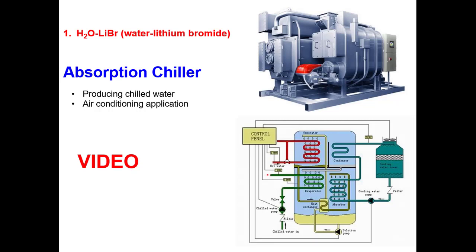can take the heat of that chilled water, I mean the chilled water entering from here. The outlet temperature of normal tap water is about, let's say, 15 degrees C, right? And the water refrigerant produced in the evaporator has a temperature of 4 degrees C. So there is a large temperature difference, and we can cool that water down as chilled water to, let's say, 7 degrees C, or sometimes 6 degrees C.